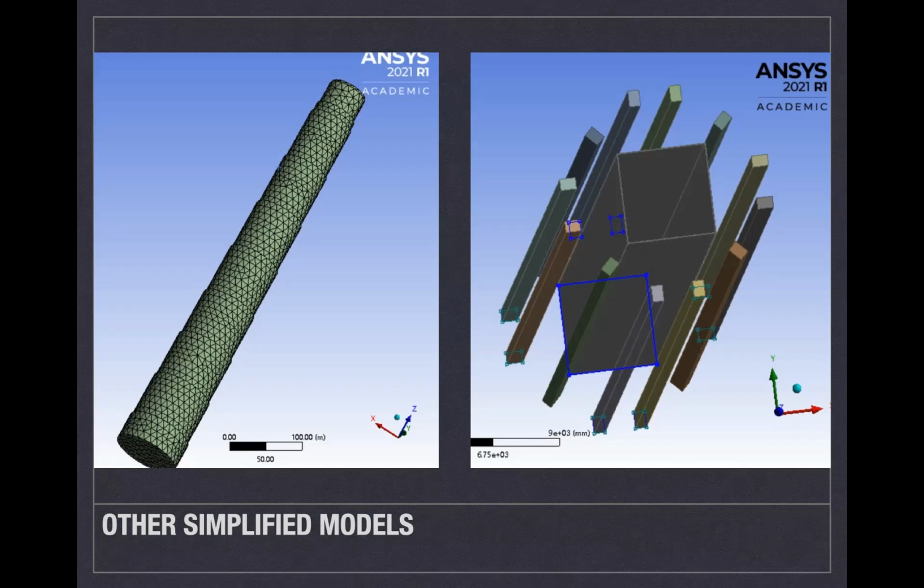The core tube is the square structure in the middle, extruded up, and there are 8 side posts, 2 on each side of the core tube, and there are also 4 corner posts. It's pretty amazing that only these 12 posts and the core tube cooperate to bear almost all the weight of Shanghai Tower, and that was super amazing.